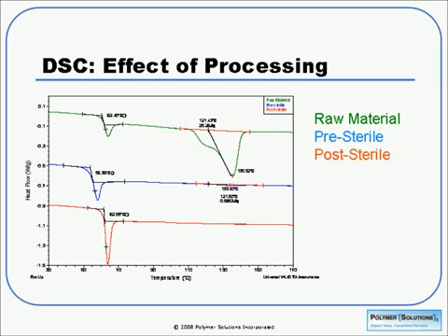We also see an endothermic peak overlaid on our glass transition, and this is related to physical aging. We've mentioned free volume of our samples. Well, if you get up near the Tg but not quite to Tg, the chains have the opportunity to move around a little bit and get rid of some of that free volume or space between chains, and this is manifested in this kind of a peak. The size of that peak is indicative of how much the sample is aged, and if we went above the Tg, that would be erased, and we'd see a step transition only.